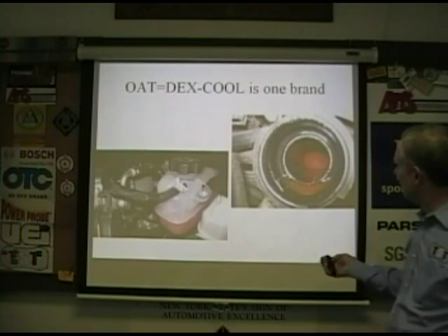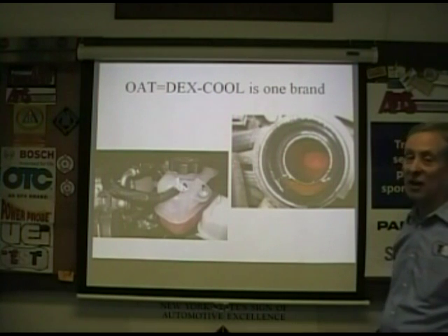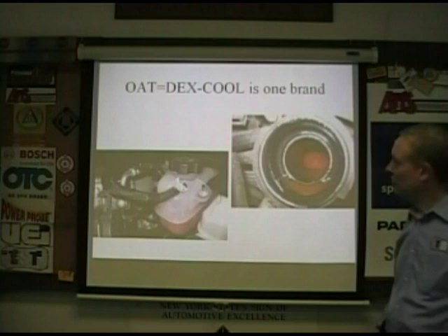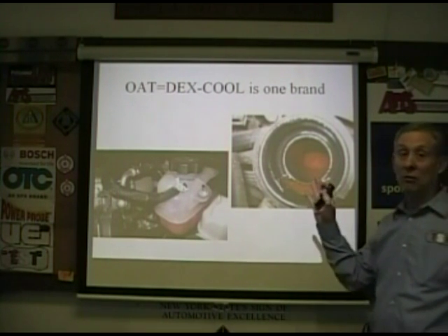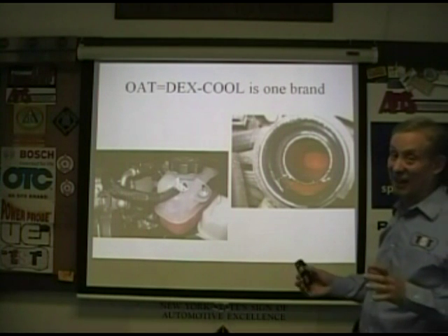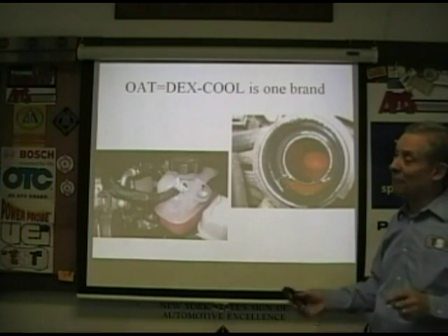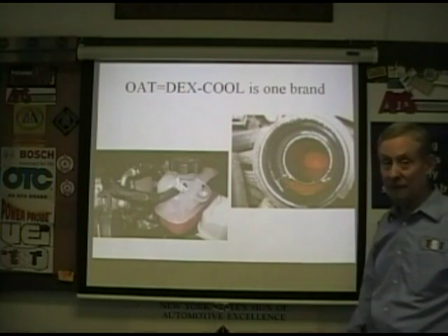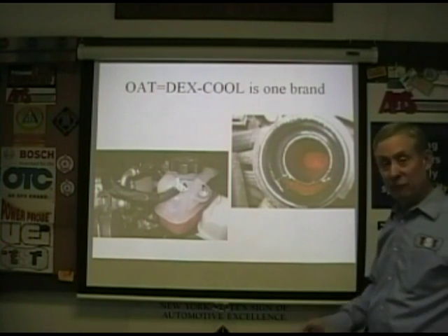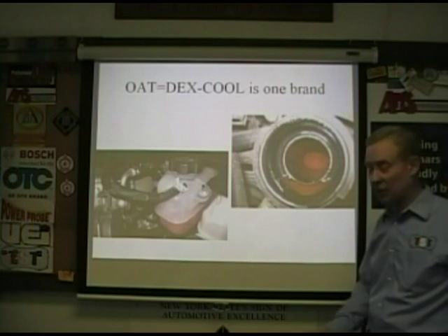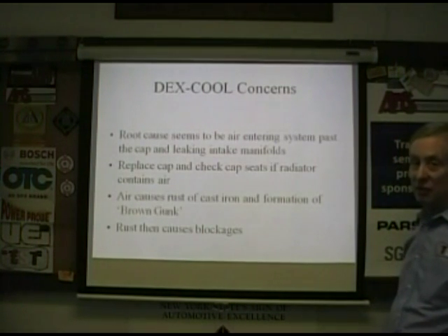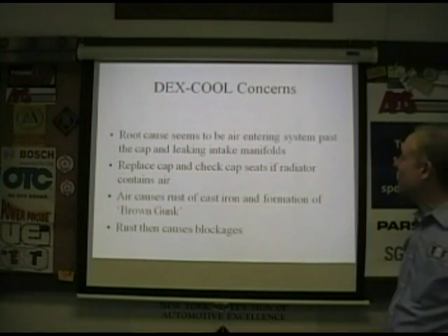If you see a color in there and it's what you're supposed to have and you kind of know the history on the car, you can add makeup coolant. If you don't, sell a flush or don't touch it. Don't get stuck in a situation where you put a thermostat in that car, drain some coolant out, put the right stuff in, it's now incompatible, and the engine ends up with jello and an overheat and needs a motor. Tell the customer you cannot do that job unless you flush it. Otherwise, you know, you're the one holding the bag. Okay.